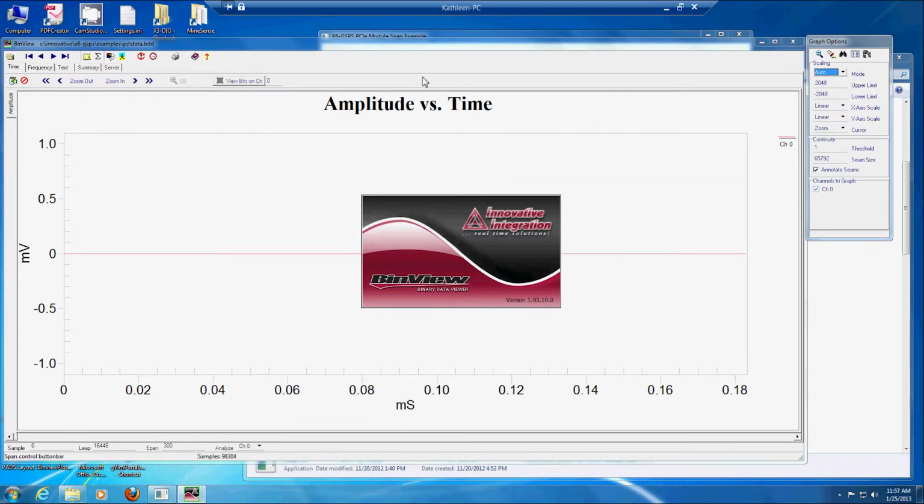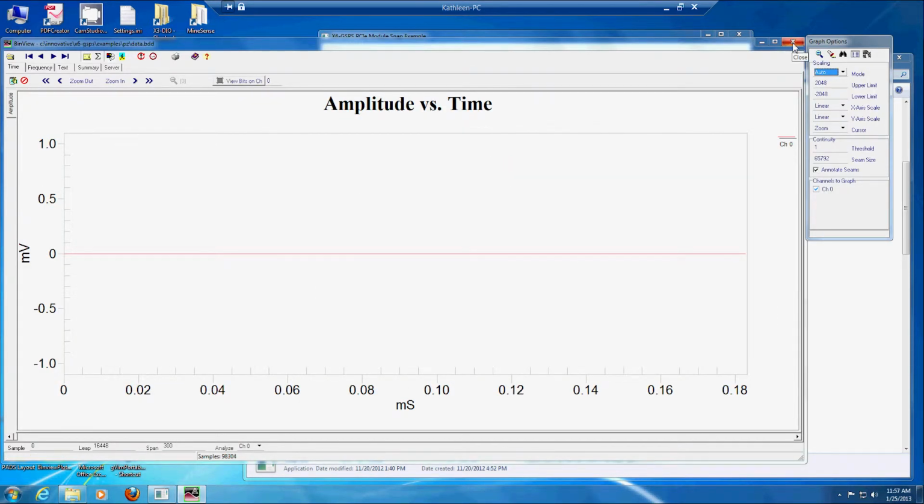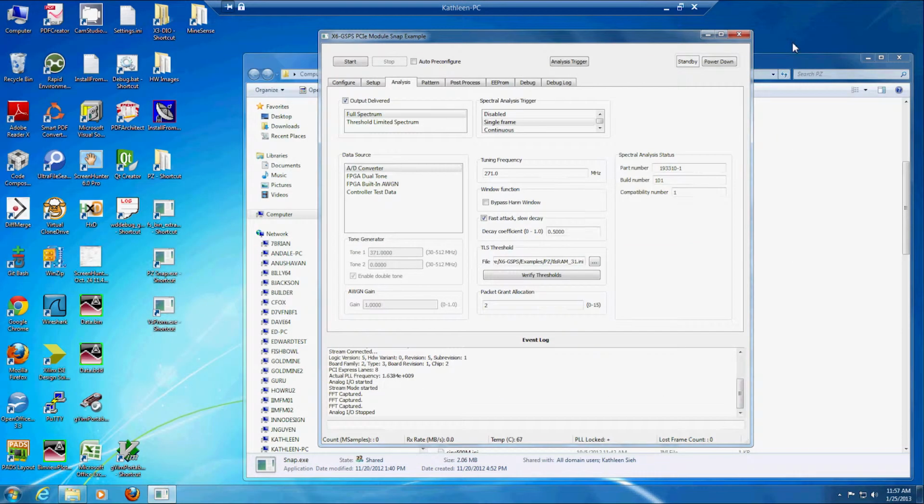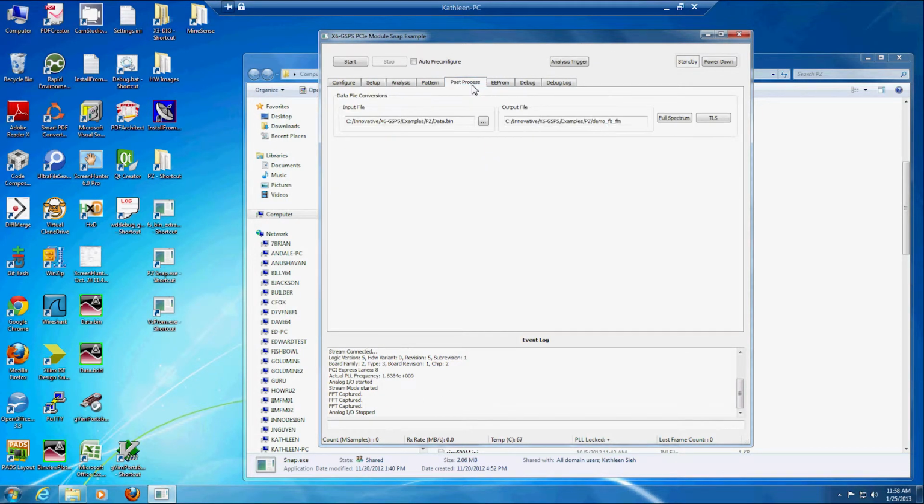I close down the default plotting data because this particular implementation requires very low latency. Therefore, the FFT outputs are not provided in natural order, and instead frequency bins are output in bit reversed order. To view a plot of the data, some post-processing is required. We select the default logging file and give a name for the processed file that we want. A full spectrum report is indicated.